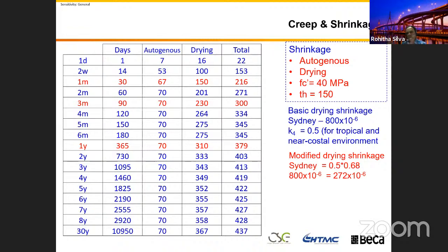That goes back to your articulation and calculation. My advice is that it doesn't matter what code you use; they are straightforward because the approach is clearly described. You calculate with the parameters, develop this table yourself, look at the numbers, and draw the graph to see how creep and shrinkage behave over time in your particular bridge element.